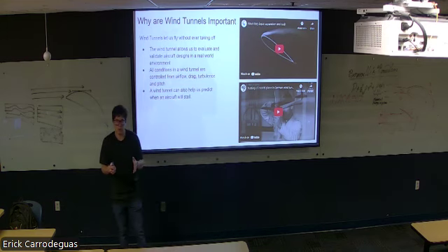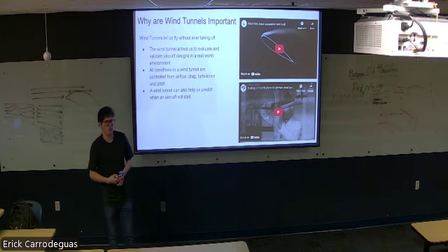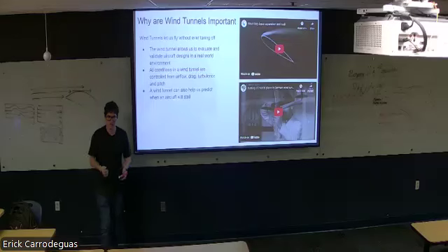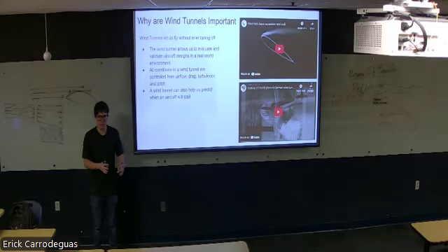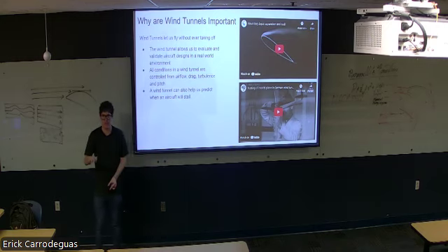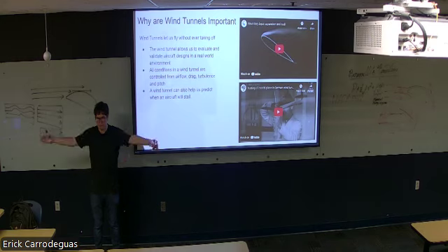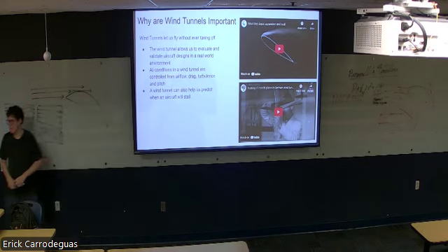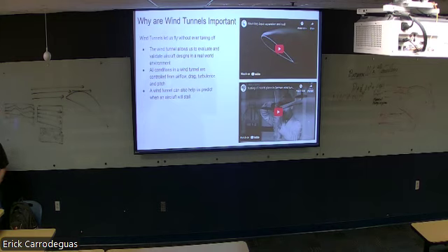When we scale it down, we also have to scale down the Reynolds number, right? A bigger Reynolds number is aimed for a bigger plane, and a smaller Reynolds number for smaller planes. So if we can use the right Reynolds number with the right scale of the plane, we could basically test the plane as if it were as big as possible. But that's important. So here is basically a video on stall.